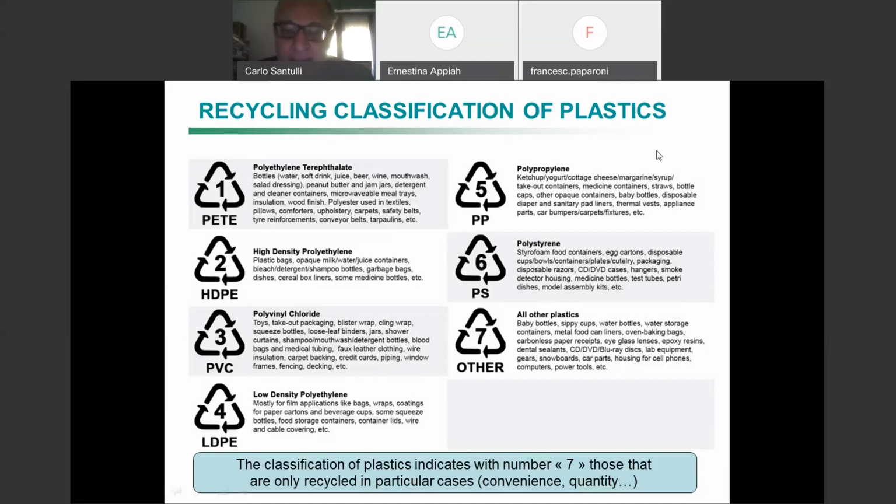We have trouble with number three, which is the polyvinyl chloride, which is the oldest one in historical terms, because it was used already in the 30s, and so before the war, and it contains, as the name says, chlorine, which means that once you reprocess it, you are likely to have an environment which is going to be heavily acid or basic, and so it's difficult to control the pH, and it's difficult in many cases to reprocess without having chlorine emissions, etc.